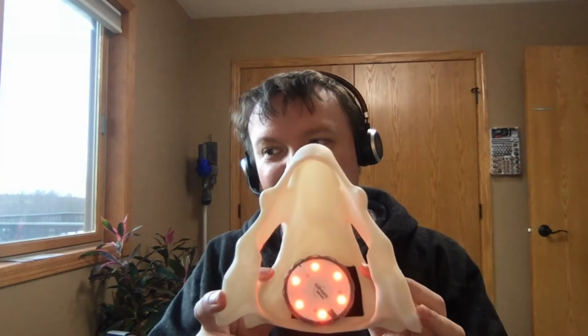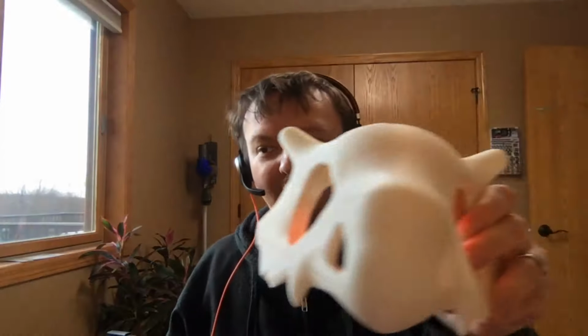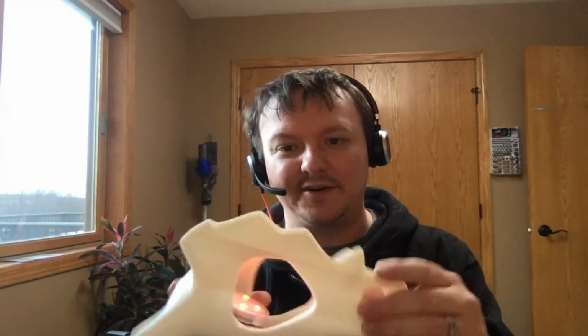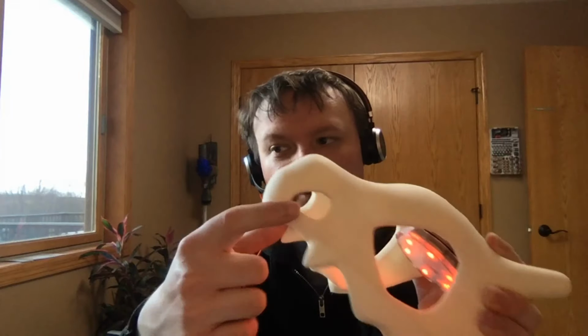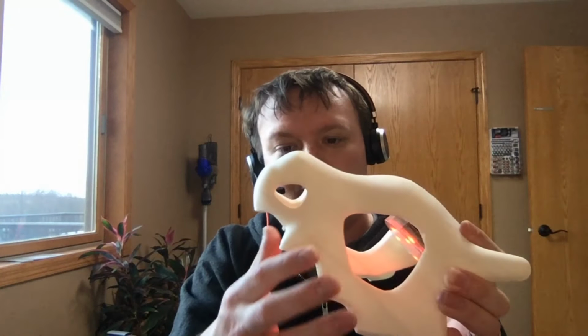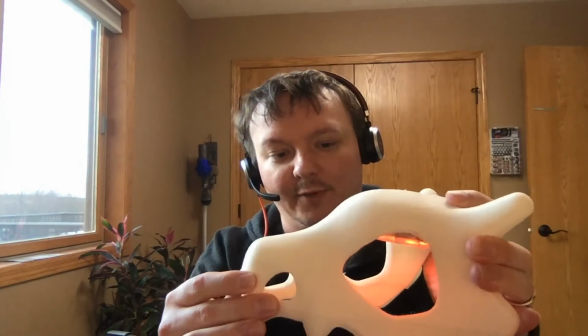He also has a LED light inside of him. So he sits on the top of my steps like a gargoyle, and he was out there for Halloween. So I had an ominous glowing Cubone skull. And this turned out really well. It took a very long time to print. One of the things is I had to do them in two parts. So you can see there's a little bit of a line here. It's very hard to print this teethy bit. There's not a lot of surface area to hold it if you're trying to print like this. So by splitting it along this line, I was able to print the top half perfectly well and the bottom half perfectly well, and then glue them together later.